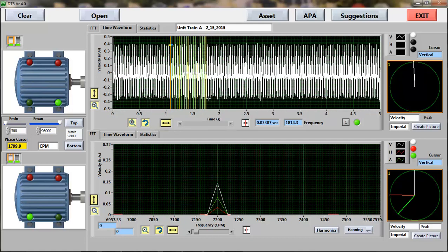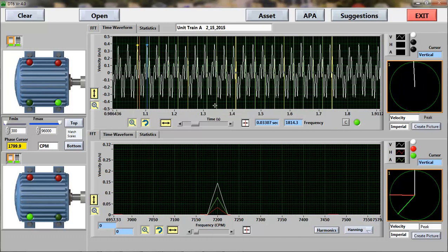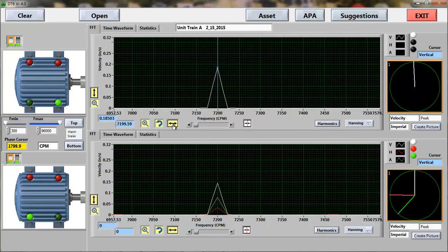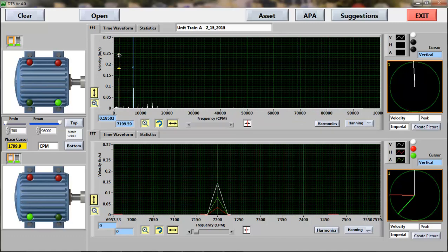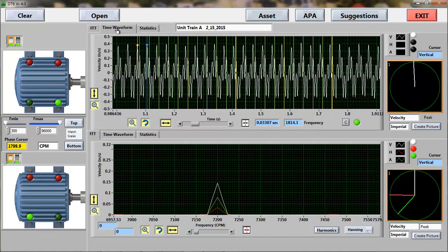Let's zoom out, so we've got a number of those. And what are they all telling us? They're telling us, again, from a repeated cycle standpoint, what's going on for this given frequency, and this spacing is all based on what we have set here for our phase cursor. This phase cursor is telling us a given frequency and therefore spaces that frequency here with this.